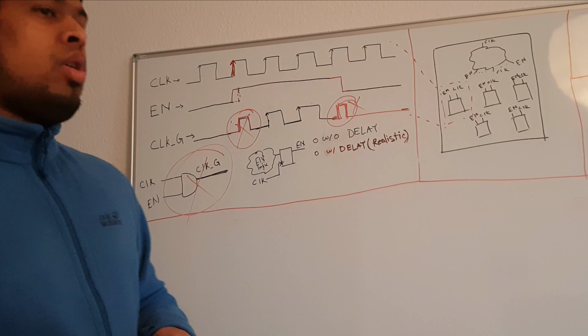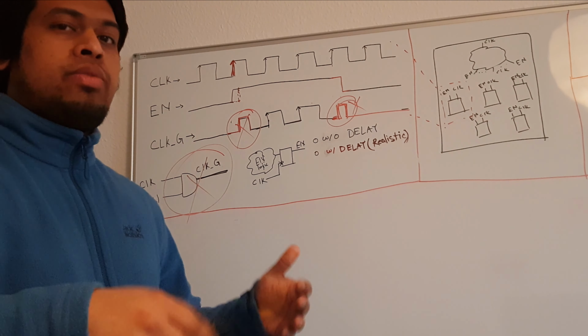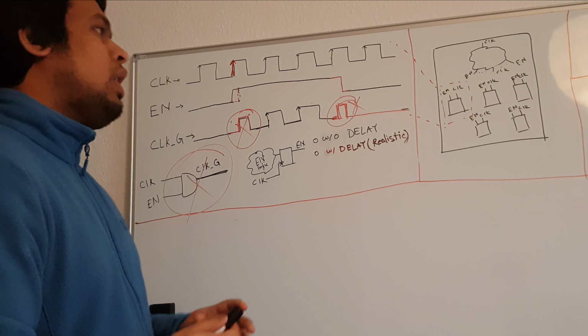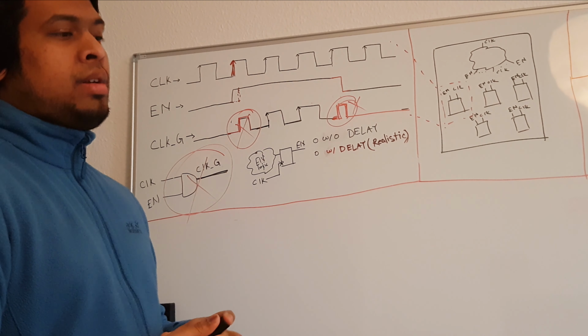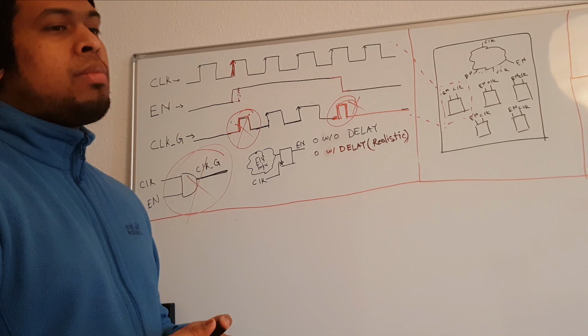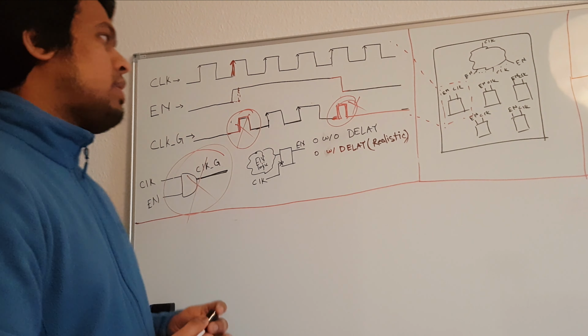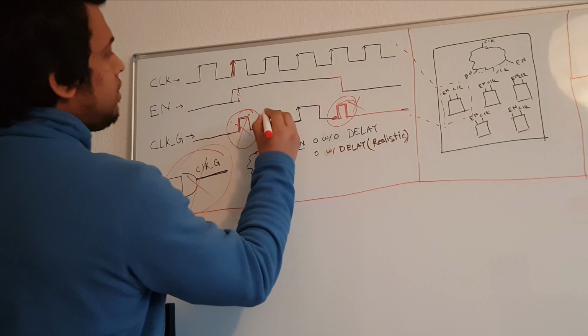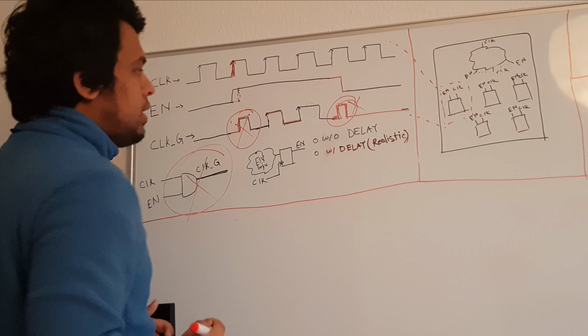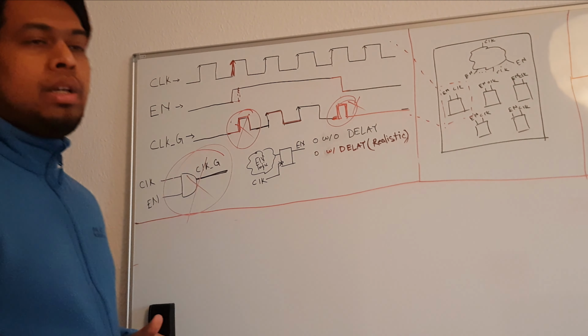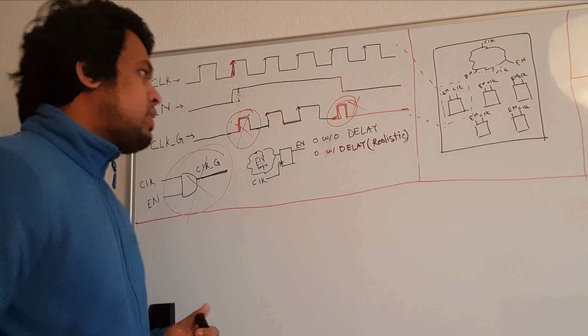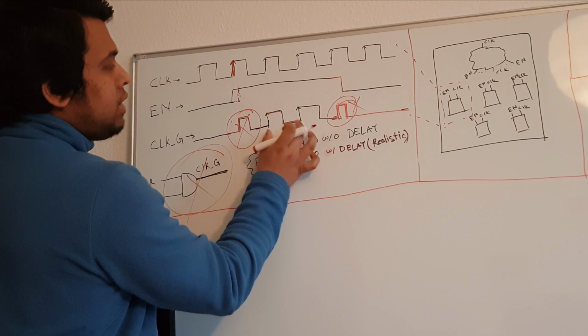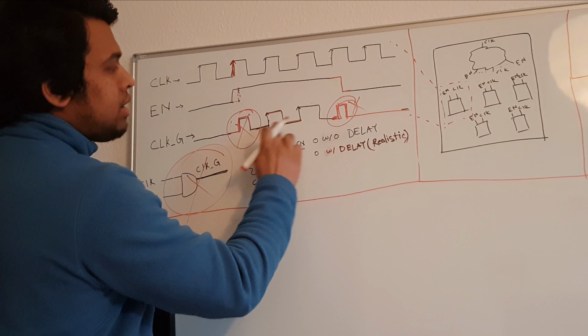when a clock is actually specified in a project or a design, most of the time there is a term called a duty cycle. So here it's actually 50-50, so we say the duty cycle is 50. If the duty cycle is 25%, that means that of the whole period, 25% would be high and the rest will be low.